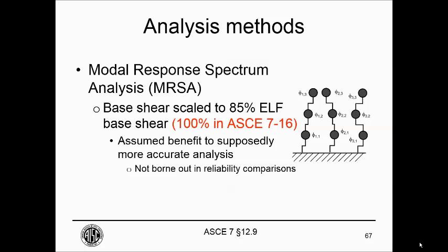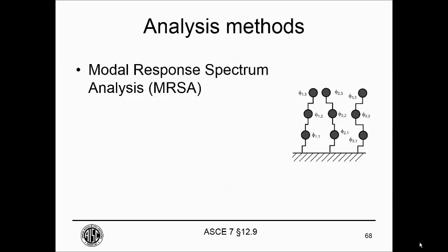It hasn't really been borne out in any reliability study, and that's one of the reasons that 85% was increased to 100%. Regardless of that, there tends to be far less overturning for the modal response spectrum analysis forces compared to the ELF forces, so there can be some economy there.